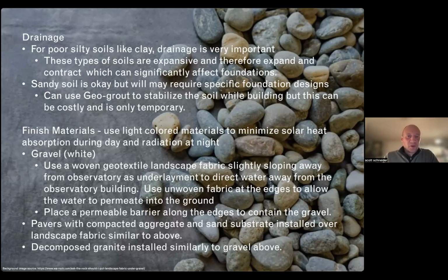Okay. So drainage is another important factor for foundations and for soil. It's really important, and it's very helpful to keep the water away from your foundation. Obviously with silty soils, it's even more important. You want to try and move any bit of water away that you can. Like in your house, you probably have drainage tile, and in some places you may have to have a sump pump to pump it out and get it away from the foundation.